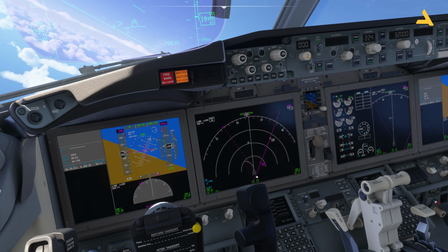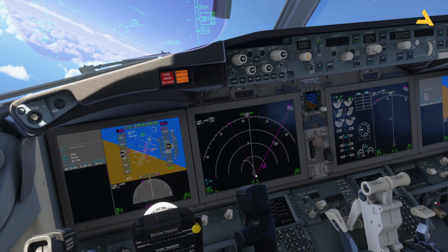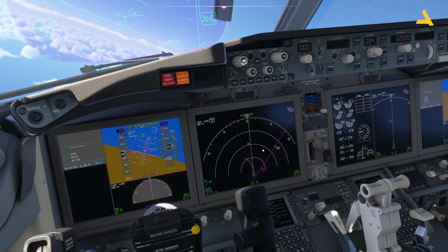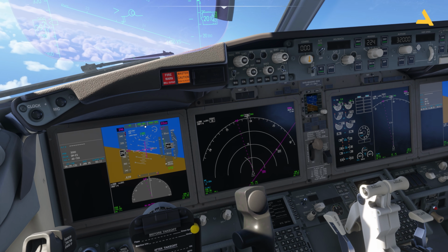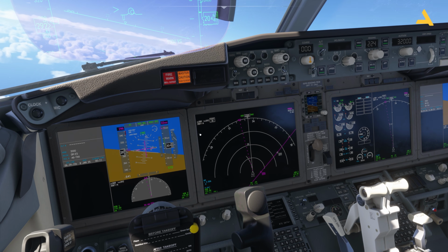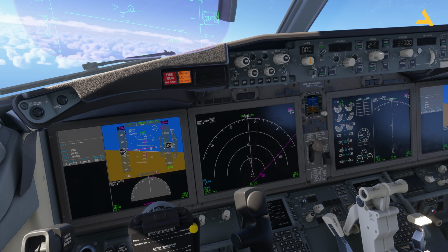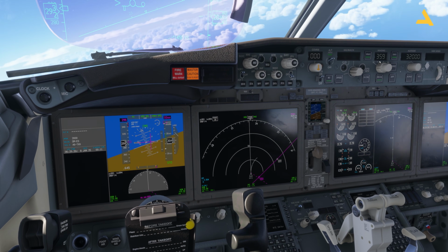So now let's wait for 2 nautical miles of deflection towards left. And right now, if I press LNAV, you will see the plane will not go back to the flight plan. Now the heading select is active and LNAV is armed. And if you want to go back, you then have to change the heading. So let's change the heading and try to intercept this line.